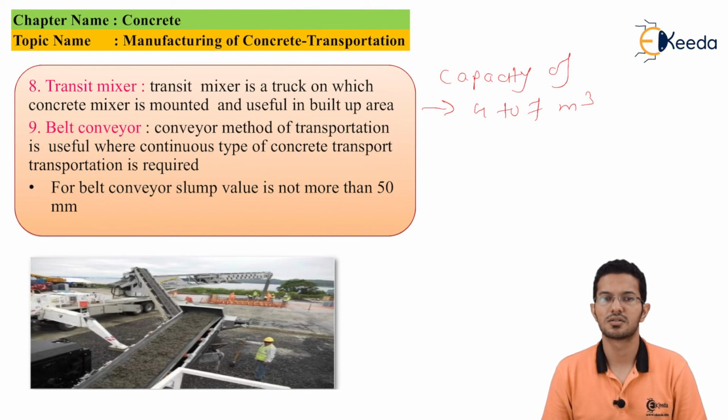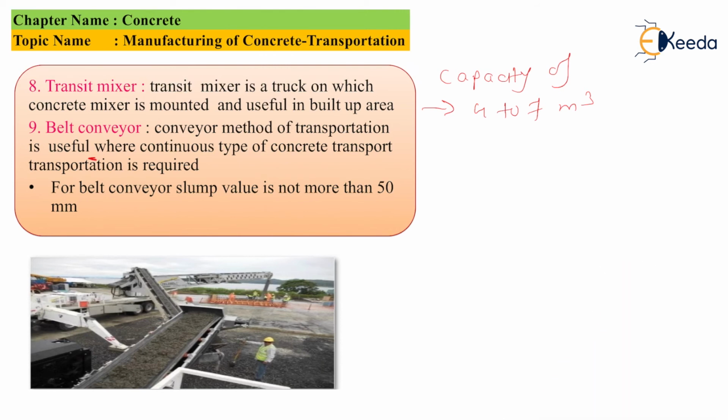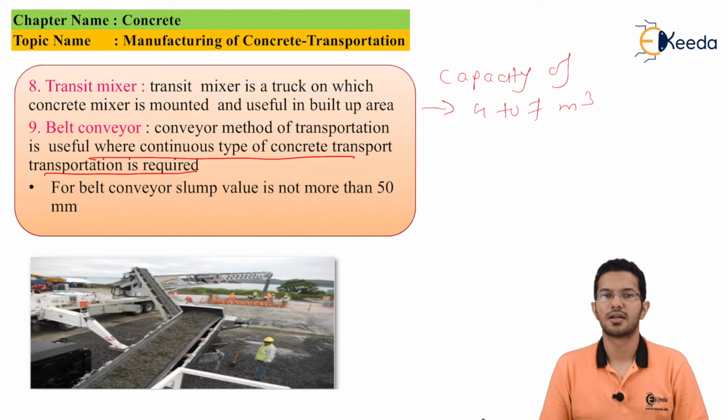The belt conveyors are used for a small horizontal distance such as 5 meters to 10 meters. The initial cost of setting up the belt conveyor is high. It can place large volumes of concrete quickly where access is limited. Concrete may segregate on steep inclines as the belt passes over the rollers. It is suggested that low slump concrete is used for slower moving belts and higher slump concrete for faster moving belts.